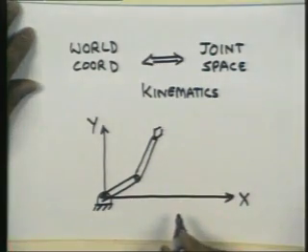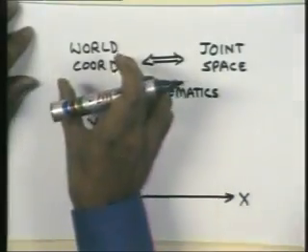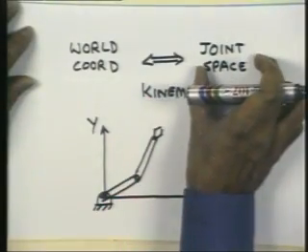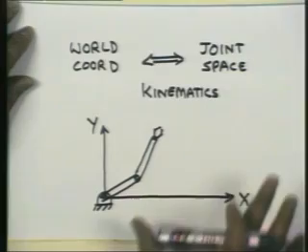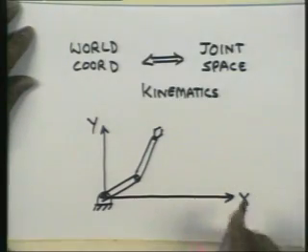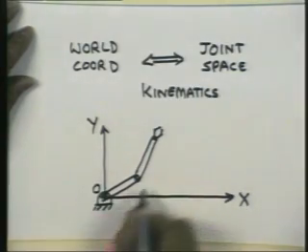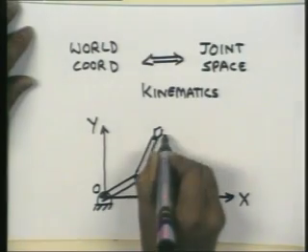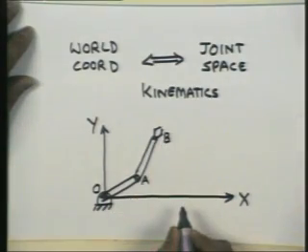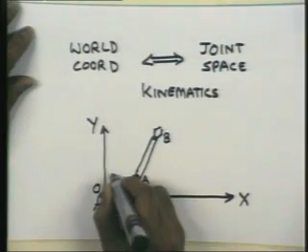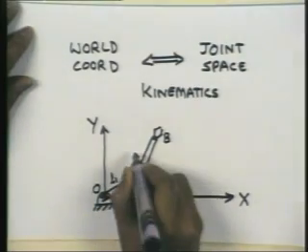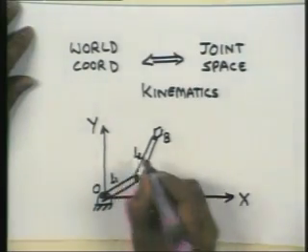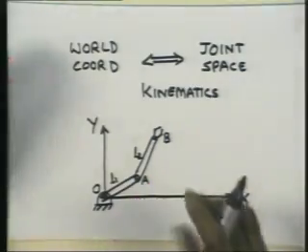Okay. You want to relate the end effector's motion and the individual joints' motion, say. This is a very simple example of a planar manipulator. Let me call this point O, this point A, and let this point be B. Let this link length OA be L1, and let this link length AB be L2. Once you have designed the robotic manipulator, the link lengths L1 and L2 are known to you, and this is a 2 degree of freedom mechanism.